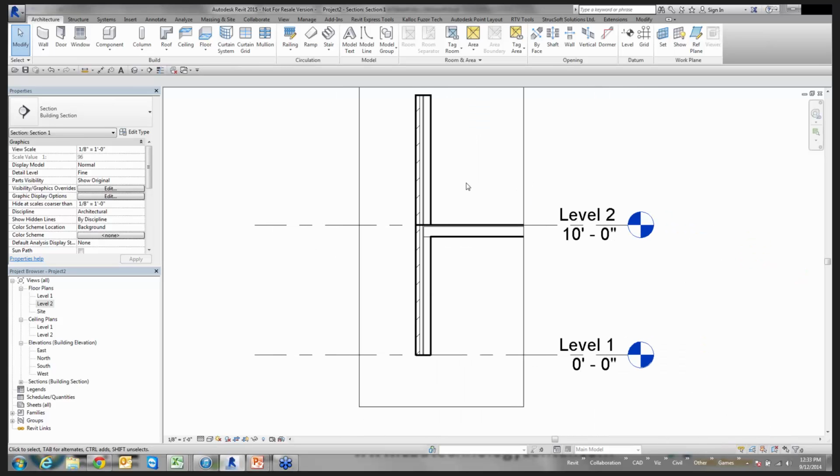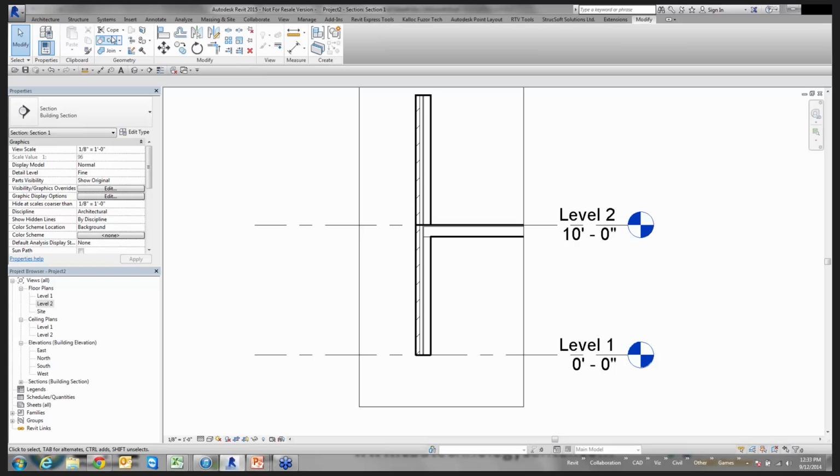For a lot of residential home builders, because it was easier on the detailing and easier on the modeling, we just said, hey, if the finishes are the same on the outside, run it all the way up to the roof or as high as you can go, and we'll cut out the overlapping geometry. With this process, you won't be able to do that anymore. So I'll go ahead and you can still clean it up so that it looks a little bit better.